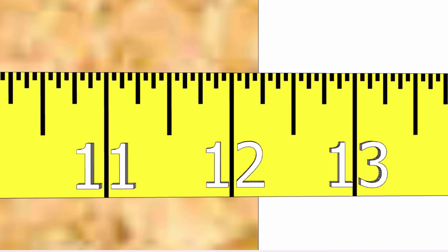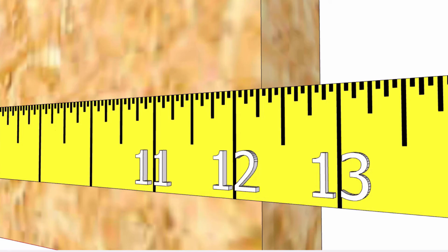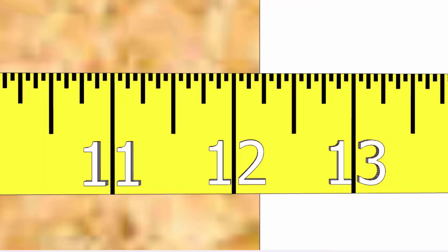At Dorian Class Services, we don't record measurements to the nearest 32nd of an inch, so the correct way to report this measurement would be by rounding it to the nearest 1/16 of an inch. So this dimension would be reported as 12 and 3/16 or 12 and 1/4. If the measurement is taken from an angle, then the correct dimension is 12 and 1/4 or 12 and 5/16. No, that's not what we want. We need to do our best to read the tape measure straight on.